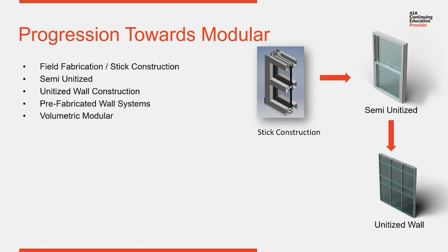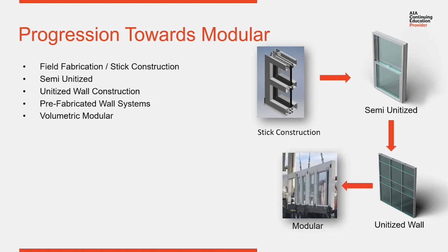Then curtain wall. A lot of manufacturers with curtain wall started looking at, hey, commercial windows have a great idea with this modular approach. Why don't we try it with curtain walls? So you saw the onset of unitized curtain wall systems where modules were built, vertical modules that span from one floor to the other, pre-assembled and glazed and carried as a pre-assembled glazed module to the job site and stacked one by one. That was successful.